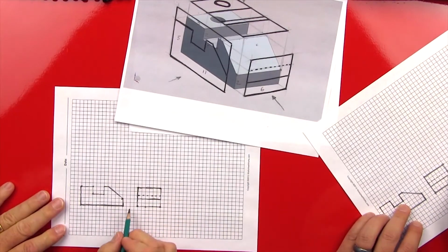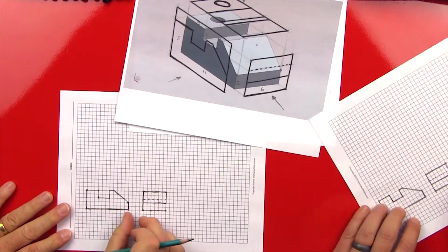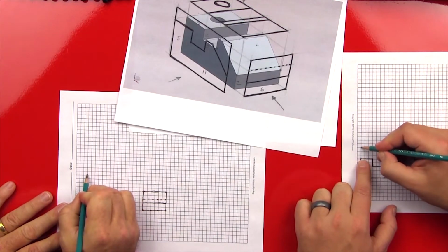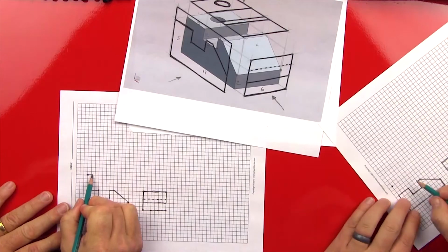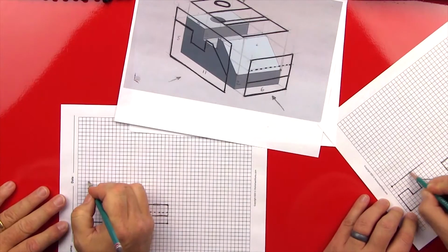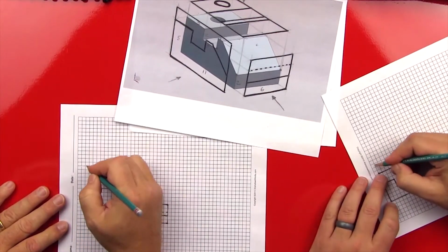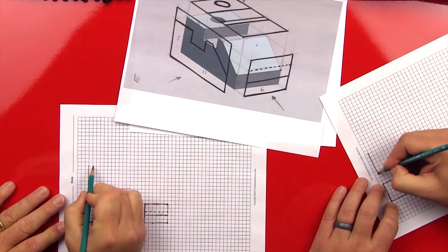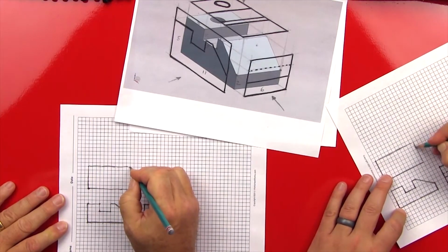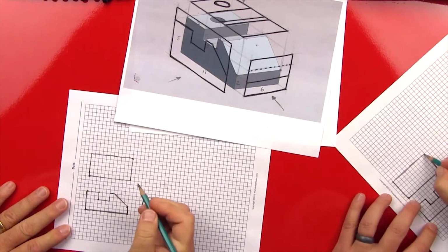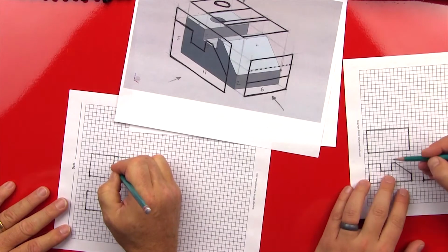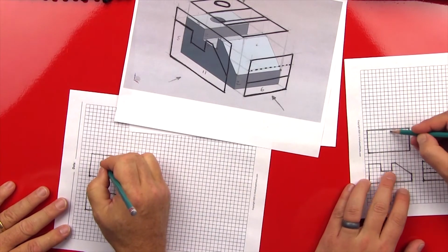And now we do the top view. And so typically what you do is if you offset this by some number of cubes, you do the same up here. And so you start off and you know that this is going to be that long. You just go all the way. And then you count 2, 4, 6. So graph paper really helps mechanical engineers quickly come up with their sketches for orthographic views. And you can just project these without even counting.